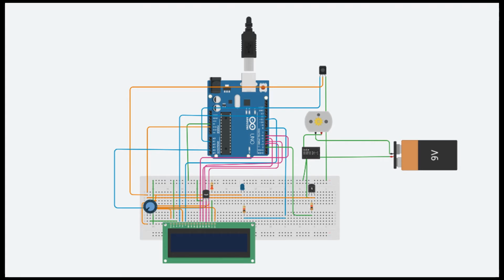Signal connects to pin A1 and receives the signal from the coding. An IR sensor needs 5 volt for supply, and it can take the supply from the Arduino Uno, which can provide 5 volt for supply.